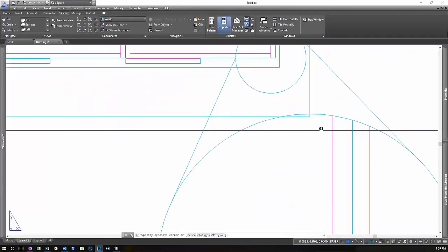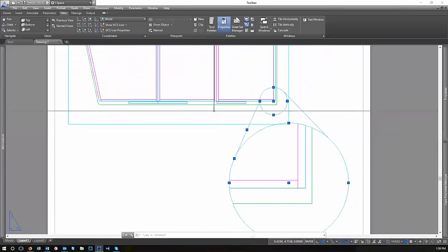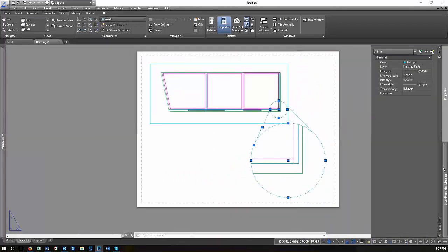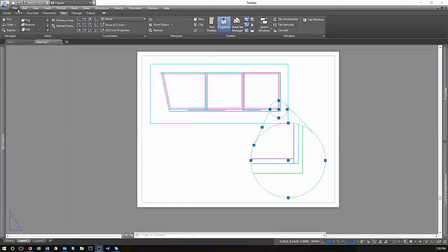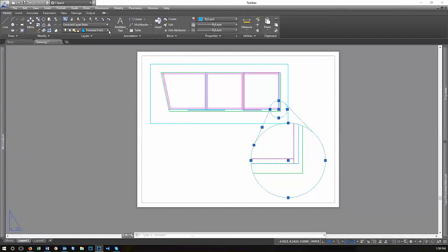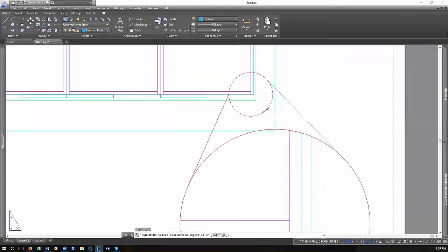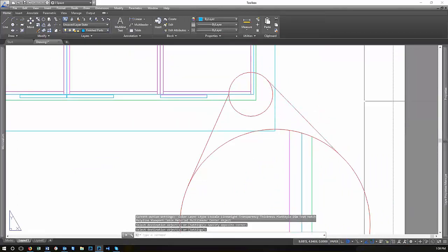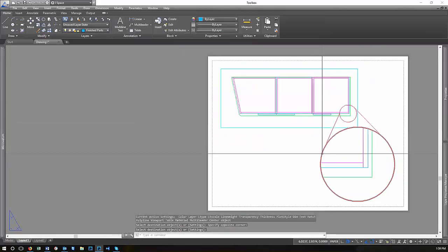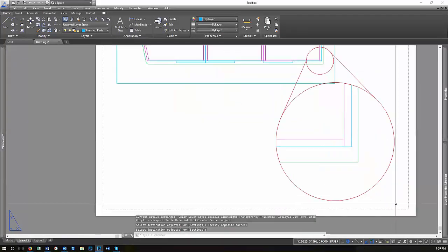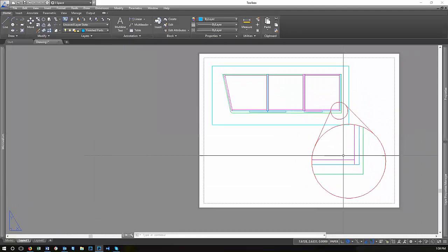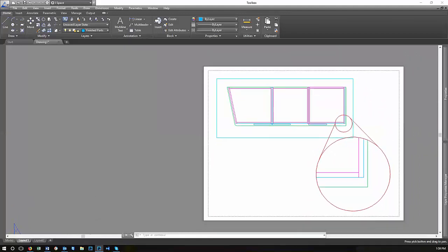And now I just move these objects to, except for that viewport, I'm going to move it to, got to go to the Home tab, move it to the red layer, which is title. And I missed one, so let me match properties to that. There you go. Okay, so we've got a round viewport, and I've got this area.